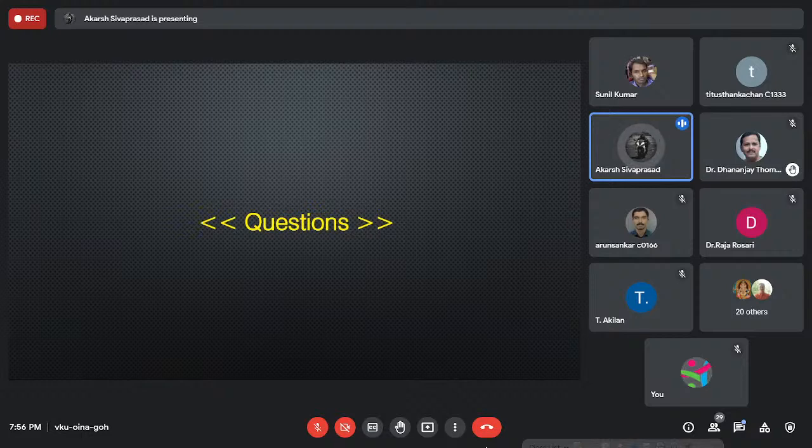One of the most common techniques is selective laser sintering, and there's also electron beam melting (EBM), and inert gas deposition. But the most common is selective laser sintering. You have a really high power laser, you raster on a powder bed, do that for X amount of layers, and then you get a part. Thank you, sir. But check out DMP on 3D Systems. Okay, sir, I'll be checking later on. Thank you.